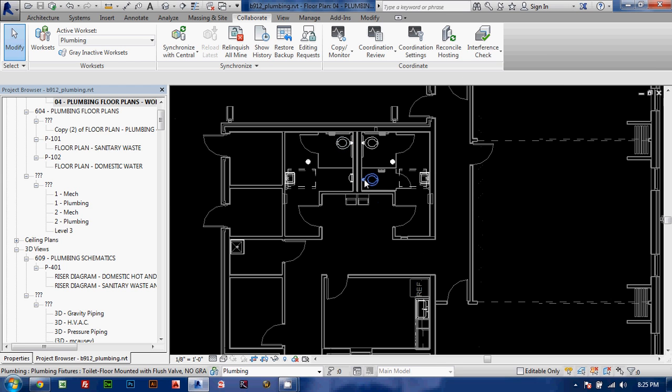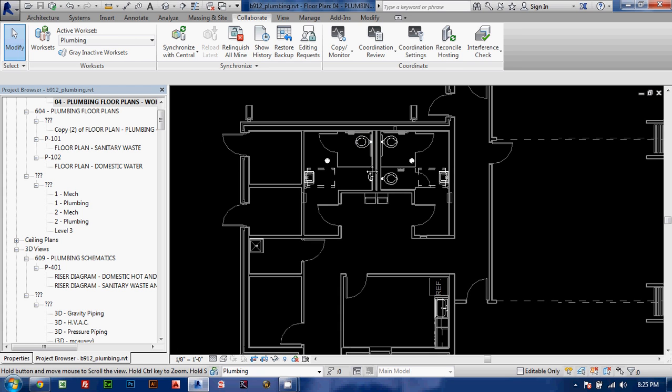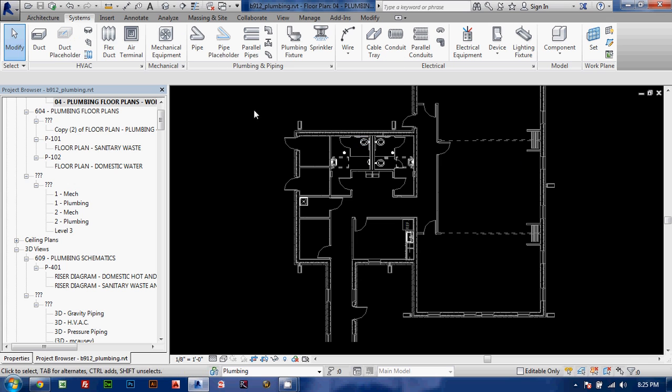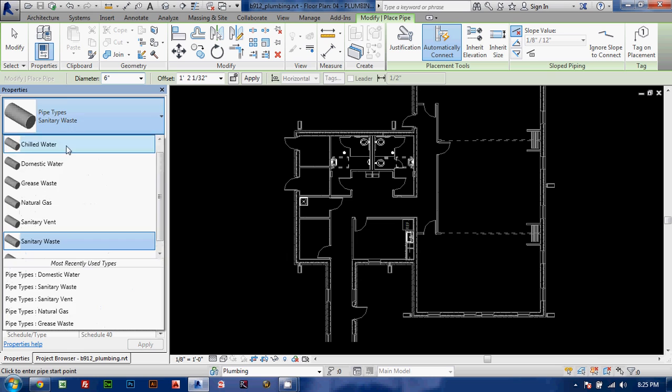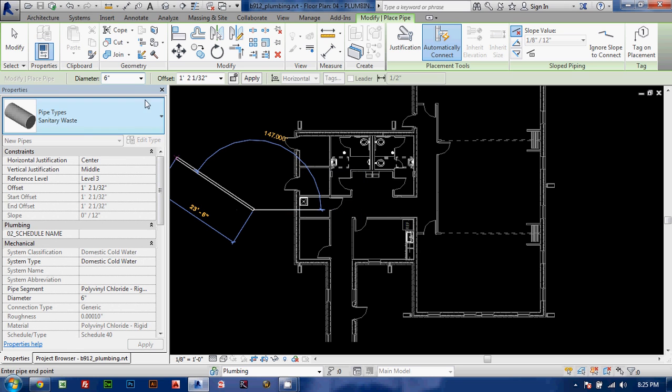And now, where does a piping system actually originate in Revit? Now, domestic water is a little different than sanitary. The workflow is different. And what I mean by that is that sanitary actually rolls out from the farthest fixture to where you're going to bring the piping out of the building. And if I were to actually start from where the piping comes into the building, I may find myself too far above the invert of the fixture itself.